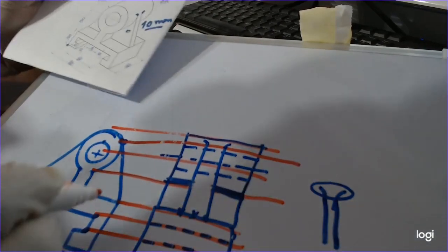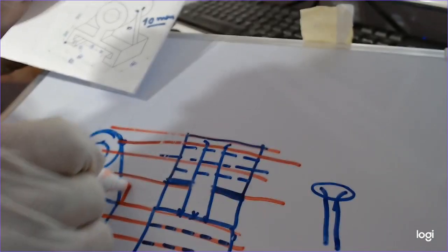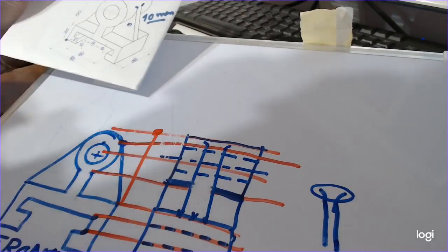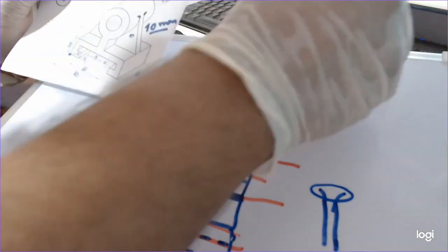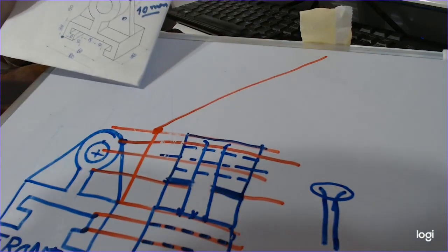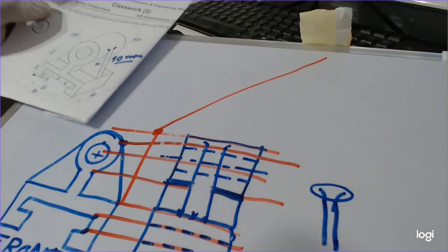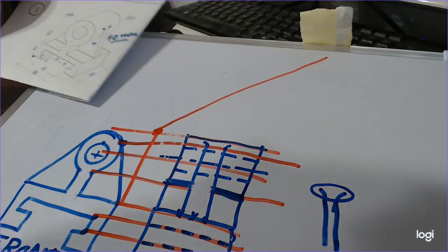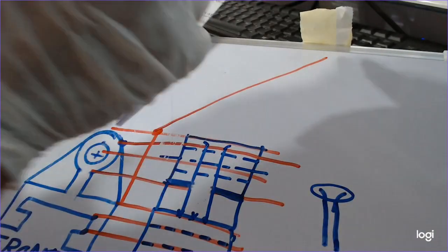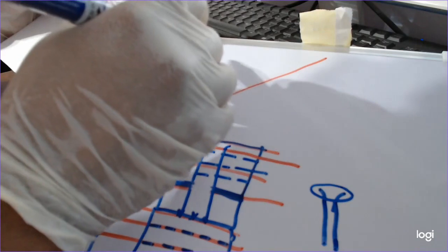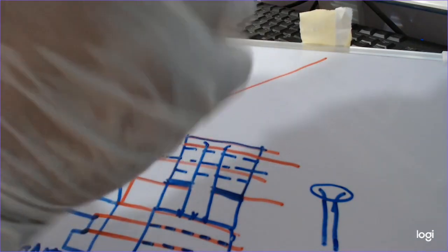To draw the top view, we'll go up from that point until we hit this virtual point, and then draw a 45 line like this one, and then start to draw the top view. So first of all, the top view basically will be something very simple. So let's draw it randomly here and then draw it with those projection lines.